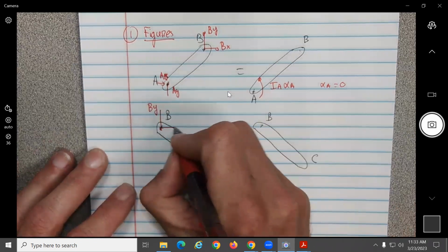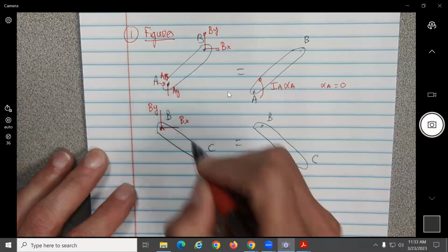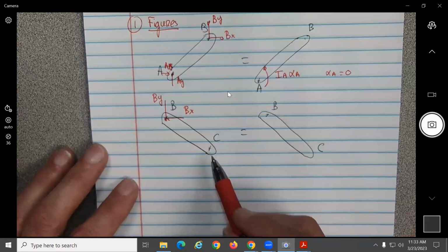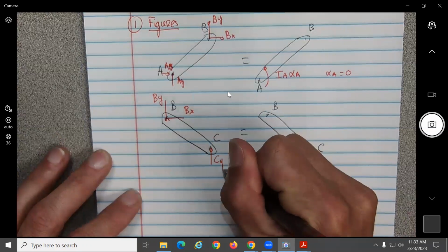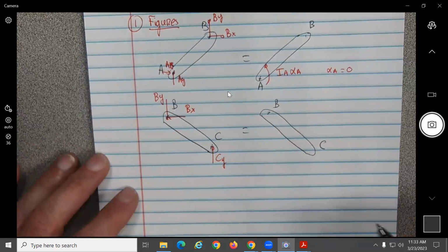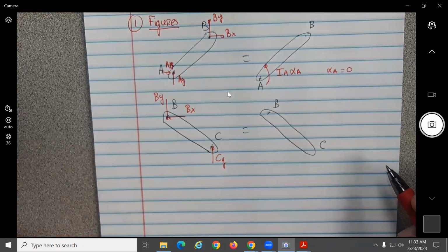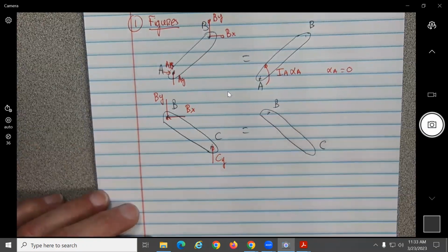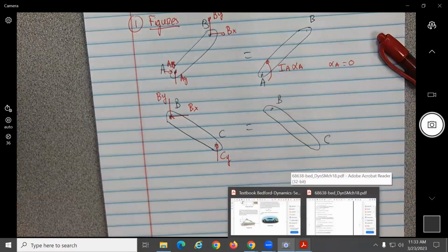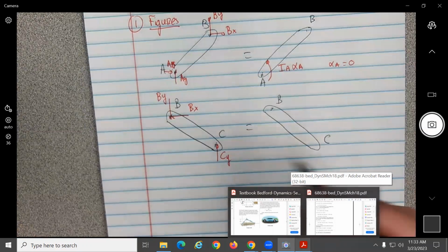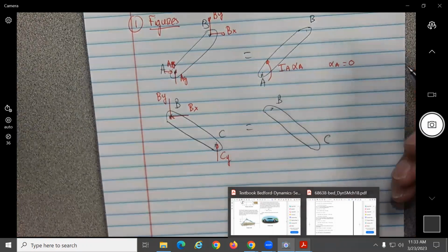By, Bx. And then what would be the only force at C? Should be the normal reaction because it's leaning, no? Okay. And also, did they provide weights on this problem? BC has mass, and not AB. Not AB. Okay, so they force you to take the moments about point A. That's what happened. You are forced because they don't give you the mass.